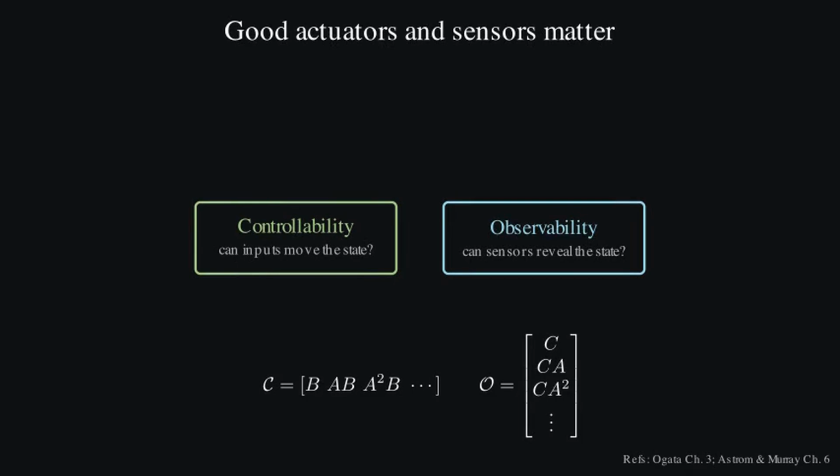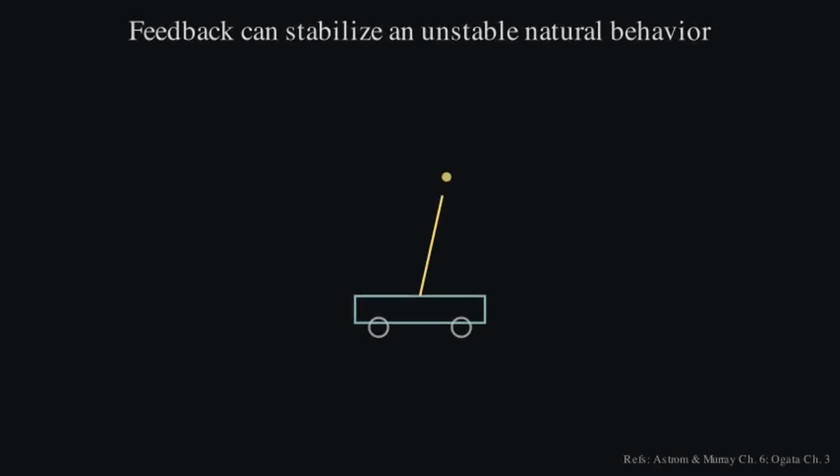Steady state error connects references, disturbances, and low frequency loop gain. A type 0 loop can have finite error to a step. Adding an integrator increases low frequency gain and can remove that step error. The trade-off is familiar now. Accuracy improves, but phase lag and overshoot risk can increase.